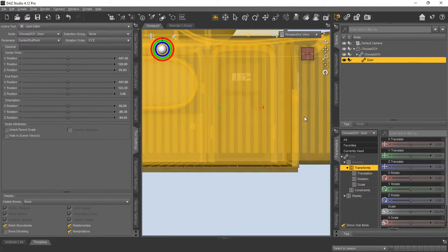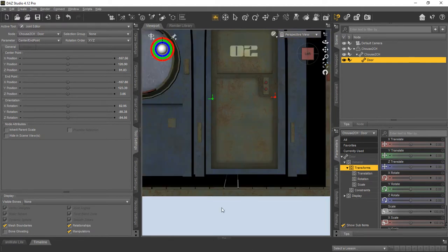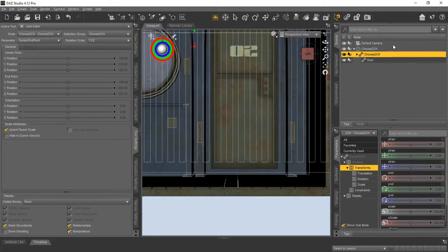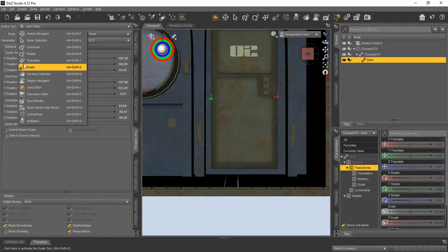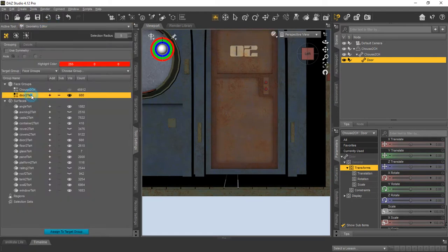Let's line these back up with the door on the left view so we can see they're off a little bit. Oops. Yeah, when you misselect, you accidentally click, and so we got to line those up to the door, because we know when we go to the geometry editor and you select the door, there it is. You know the edges are here and here.